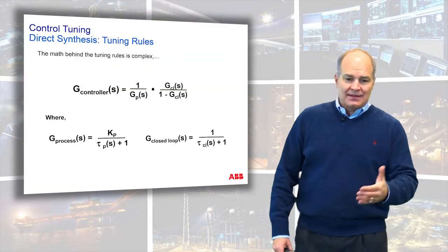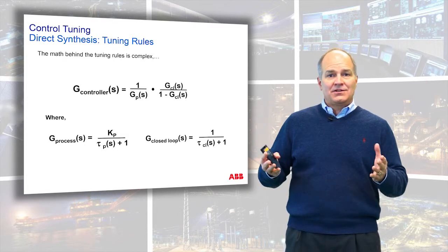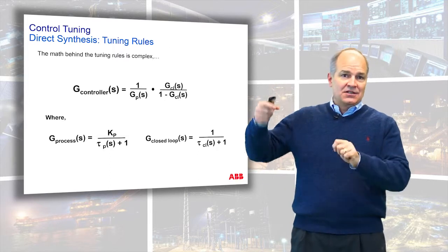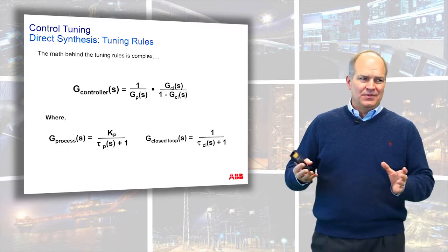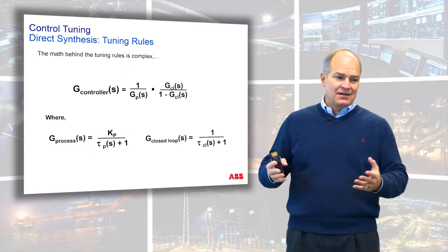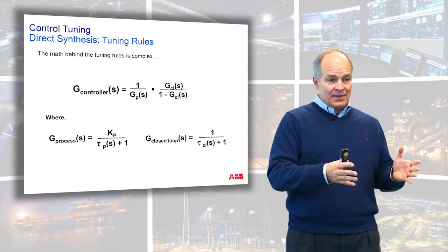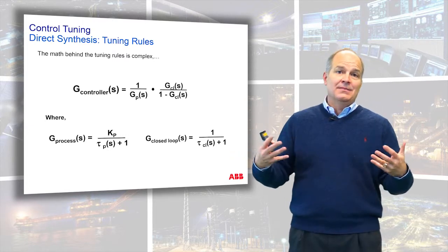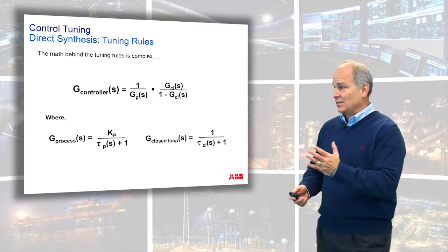The way I like to think of tuning is it's a calibration process. If you can imagine your transducer with a zero and span, if a guy's just adjusting the zero and span until it reads right, has he really calibrated the transmitter? Well, most people would say no. Well, if you're just throwing tuning numbers in until it stops oscillating, are you really tuning? My answer is no. You need to understand the dynamics, figure out what kind of result you want, and then use the tuning to match those two. That's called tuning, and that's what I find fascinating.